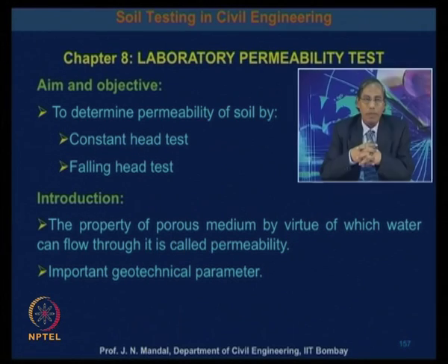The main objective of this test is to determine the permeability of the soil, and there are different methods. One is called the constant head method, which is particularly for coarse grained soil, and the other is called the falling head method, which is particularly for finer grained soil.